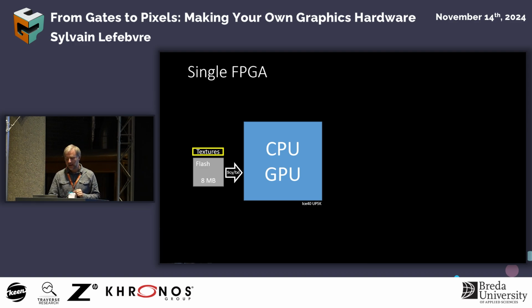texture mapping. And this is going to use a very fast memory controller optimized for random access, which means I have bindless texturing because every texel can jump around in memory, and in 9 cycles, I get the next texel value. All right, in the SPRAM, the 128 kilobytes of memory, I'm going to put the entire CPU RAM. OK, great so far.